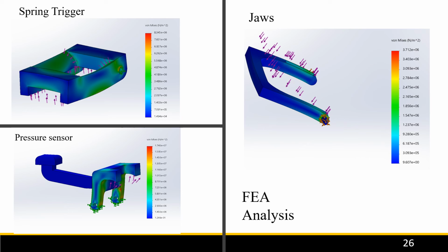You are probably wondering, how did they create such a force and what force to be applied? Well, we are using a torsion spring. The torsion spring provides about 15 newtons of force. However, we wanted to make it feel more realistic, and we gave it a range of about 12 to 14 newtons. We did not want to pass the max capacity of force that's provided by the torsion spring. In the next couple of slides, we will demonstrate how we have a fully functioning claw mechanism.